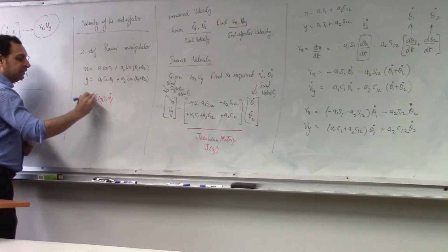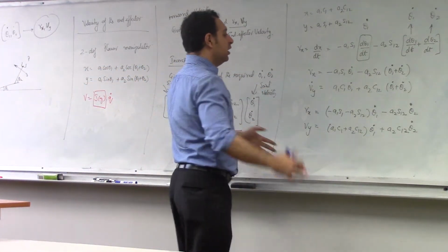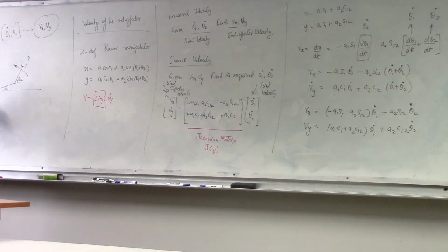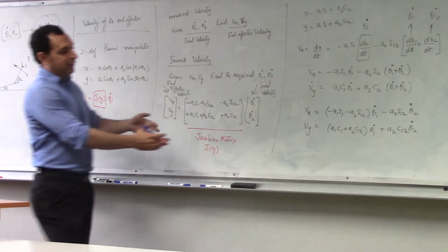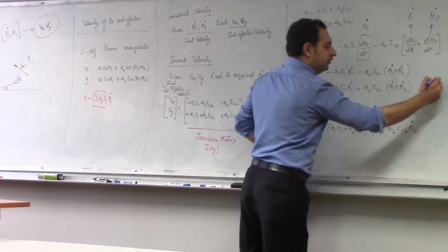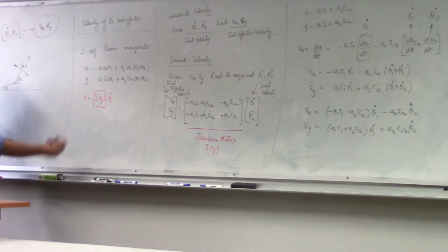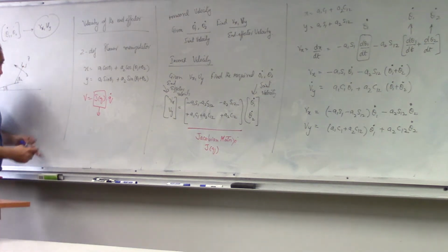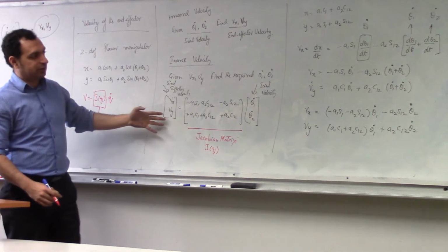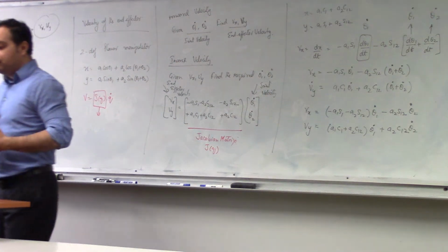In this case we derived it by differentiating, but if you look at forward kinematics equations for a 6 or 7 degree of freedom manipulator, it's not as simple as deriving it in two steps, because the thetas will go on to θ5, θ6, so you cannot do that. There has to be a different method to calculate a Jacobian, and this is what we will investigate: how to find the Jacobian matrix for different manipulators. In a simple case, we can just derive it like this, as we did with forward kinematics.